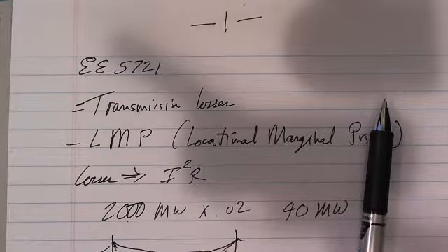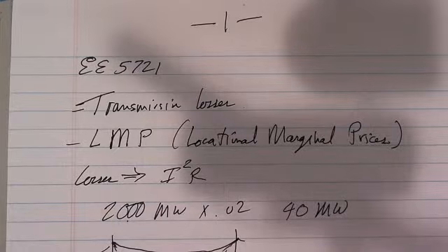They will change the limits and say, okay, we can push more megawatts on a cold winter windy day than we can on a hot day, and then they'll lower the limit on a day when it's hot, there's no wind, and it's in August, and the system is at near peak load, trying to keep up with air conditioning. That's when it gets very dangerous, because the weather's already hot, and that's when you do not want to overload the line.